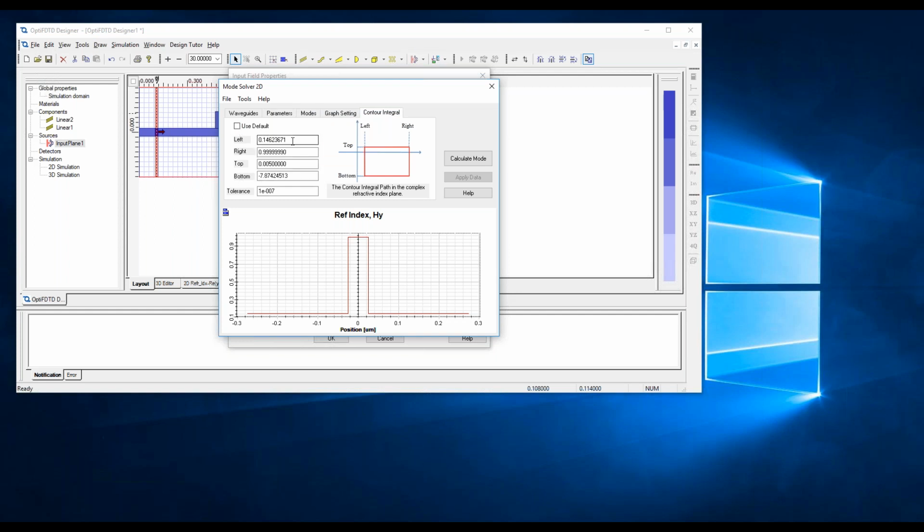It takes a look at the refractive index in the complex space. So we want to define the real part. We know the real part runs from 0 to about 2, and the complex part, this is the complex, 0.05, and we're going to run this one as -4. And we're just going to decrease the tolerance a little bit.